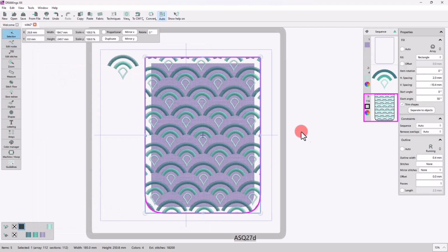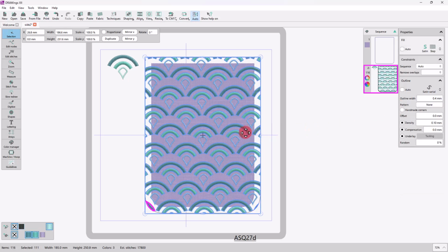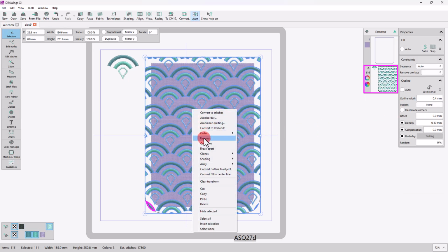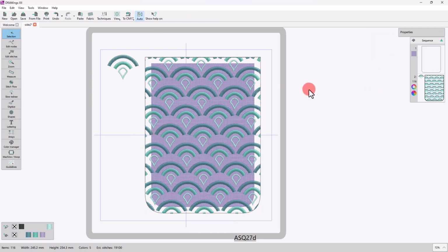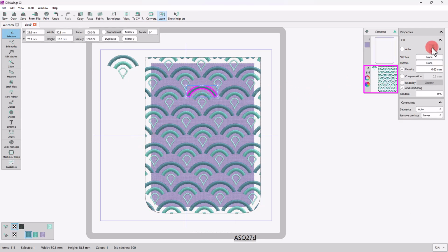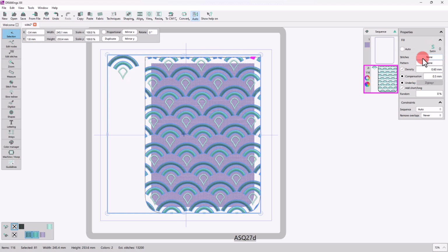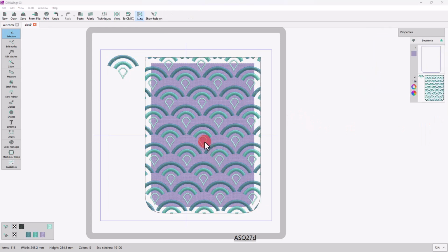As mentioned before, when designing the other side of the case, you need to separate two objects. Ungroup, and then select all setting parts and set the Remove Overlaps option to Never to avoid overlap removal, which is not wanted here. Keep in mind that in order to sew the two sides together, we need to have an additional running stitch at the end of the second side. Make sure that Add New Objects as Clones is disabled.